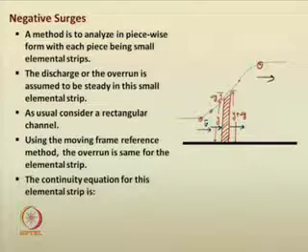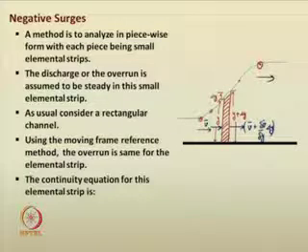And here we are considering v plus some change in velocity due to the change in depth of flow. We are incorporating it in this way. This is mathematically possible, that is del v by del y into delta y. Like that, now here we are considering the beginning of the wave, the velocity is v w1, and here the wave velocity is v w2.